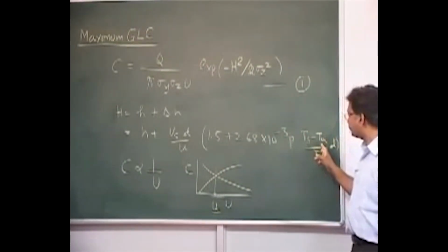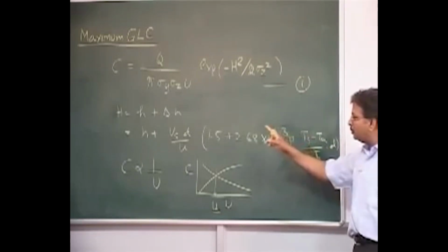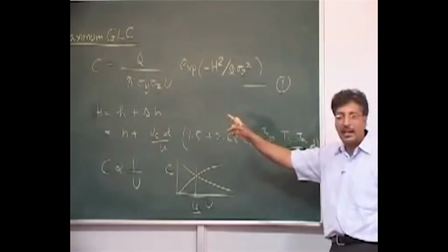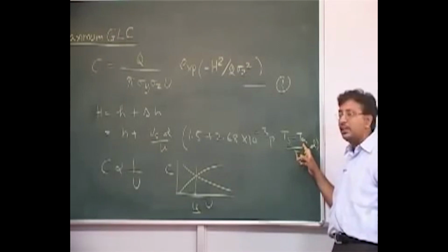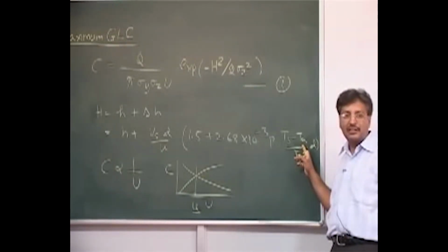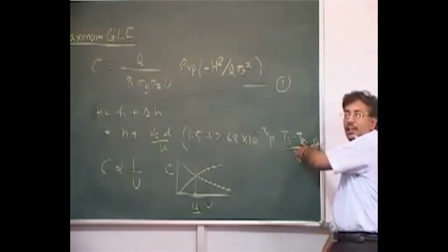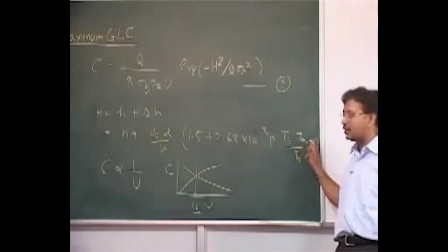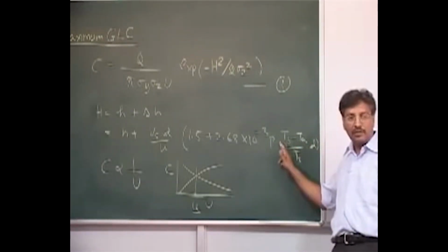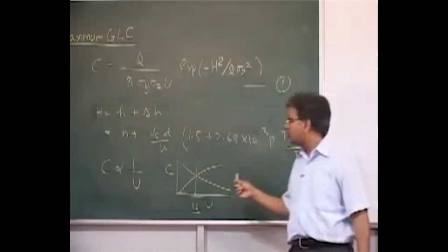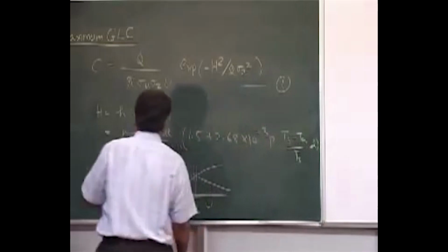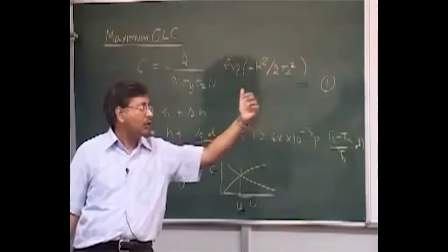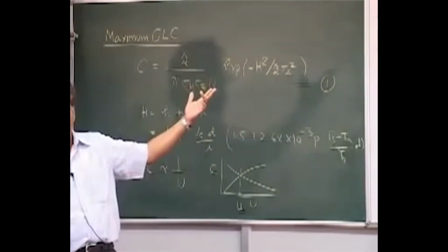And then you see here, when will delta H be small? When TA is large, because the higher the difference, the higher the H. So criticality will occur when TA is high, right? In summer conditions, so you can assume this to be high; in Indian conditions, the ambient temperature you can take as 40 degrees Celsius. So in a way I got this one fixed, this one also is fixed, nearly 1000 millibars or something. So what is not fixed really here is the U and the stability, and by virtue of this, the matrix or the double array, I am varying both of these things.